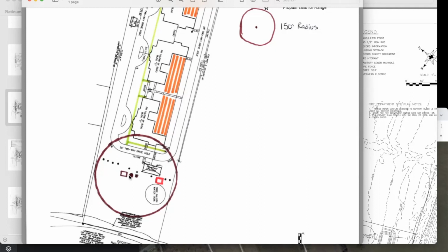Here's my well in the center, and you have to have a 150-foot radius around the whole thing where you cannot have any hazardous material. Hazardous material may be like a gas station, a pig farm, but most commonly it's a septic system. So we had to make sure our septics are not within 150 feet of the wellhead. And then here's the tank for the well. So it'll go from the well to the tank with the pump, and then pump out to the different houses there.